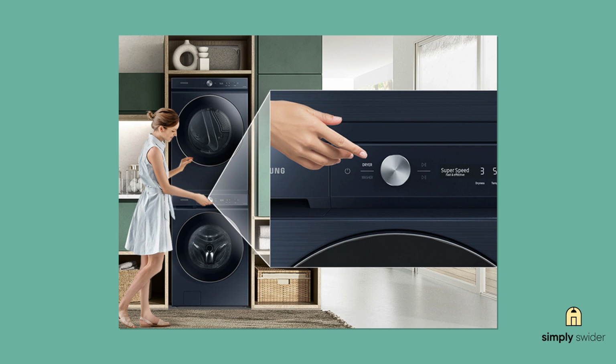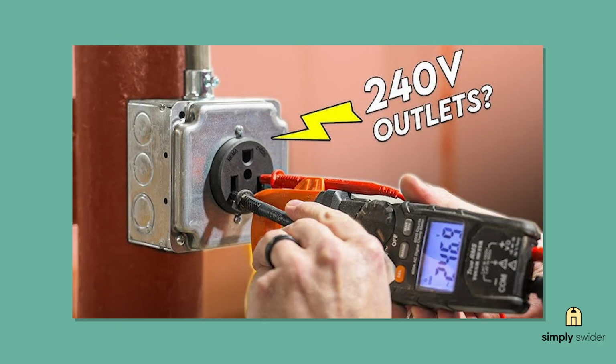Don't ask me why Samsung designed it that way, but there's actually a software update through their SmartThings app that fixes this glitch. For regular voltage issues, make sure your electric dryer is on its own dedicated circuit. Never use an extension cord with these things. Check that your power cord is installed correctly and you're getting the right voltage. If the error keeps coming back after checking the basics, you're probably looking at either electrical work or a main control board problem.